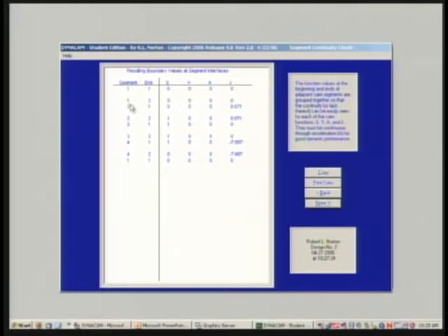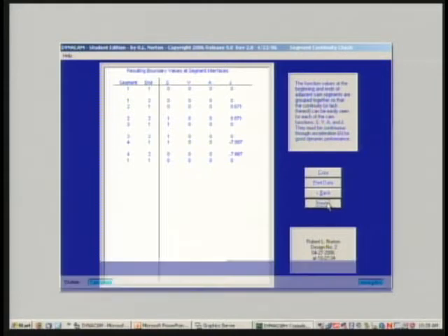This is segment 1, first end, second end, beginning, terminus. This is segment 2, beginning, terminus. So these two are the same point. The end of segment 1 and the start of segment 2 are the same physical point. They're at 60 degrees in this case. I have to have the same value of S, V, and A to obey the fundamental law. I don't have to have correspondence in the jerk. So this is acceptable, and so are these. If I see any discontinuity here, any difference in numbers, I know that somebody has made a mistake, and so do you.